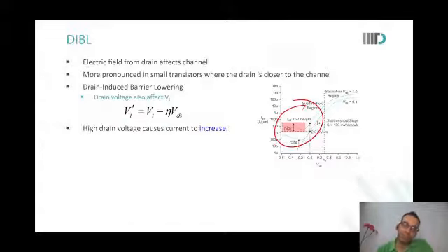But the voltage that I have applied at the gate is 0, but the doping that I could have done on the gate or the metal that I would have used for the gate can still pin it at a value such that there could be a depletion region. Might be, sir. I'm not sure. Yeah, you can study that. This is all SSD. You can read that there, and you will find out.